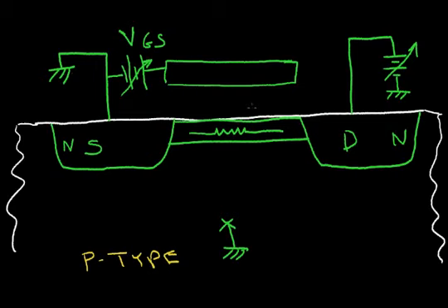Now let's ask ourselves, what happens as we increase the drain voltage? Right now we have it set at 0 volts. But what if we set that a little higher, perhaps at 1 volt? Let me erase some of this. And let's look at what's going to happen. At this part, I have a strong electric field because this source is at ground. So my channel goes down very deep. Now, as I raise my drain voltage, the electric field here becomes weaker. And so the channel is not driven down as far.